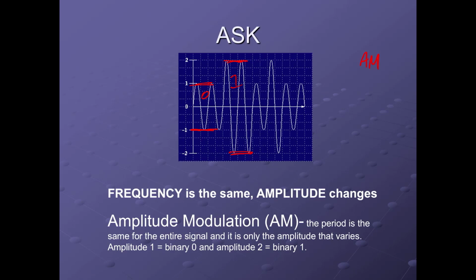And so one thing to note is if this is an AM radio station and it's analog, then it doesn't shift between two amplitudes. The amplitude or the envelope of the carrier is representing the voice or the music or stuff like that. And this is really why an AM station sounds so much more noisy than an FM station, because the noise that's introduced is interpreted as information and then decoded by the receiver, so you're going to hear any noise in the connection. Whereas for FM, you don't hear it. And if you listen to a radio station of AM to FM, you can clearly hear the difference in the noise floor or the noise level from that signal.